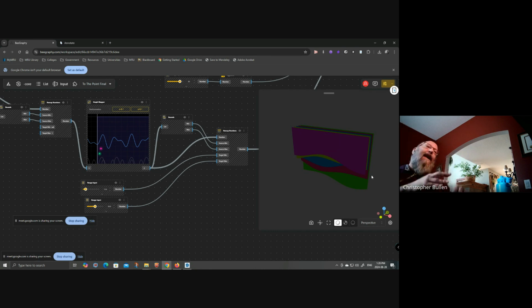But getting outside of that, if I was going to create any type of an adaptive family or any type of parametric form, I'm creating points, and I usually start with an origin, and I'll build up from there and build lines and points and lines and points till I get the end shape that I'm looking for.